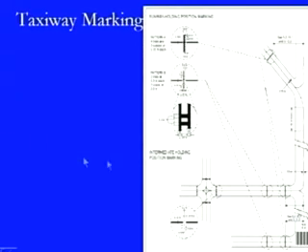This is another big diagram which tries to show the various types of connectivities. We have the runway strip on this side, we have the exit taxiway being provided at the end of this runway strip, then there is a perpendicular taxiway being provided to this runway strip, and then there is a rapid exit taxiway being provided here, by which the aircraft which is coming in this direction can move away. So, all the three conditions with respect to the runway strips have been depicted, and the linings have been shown.